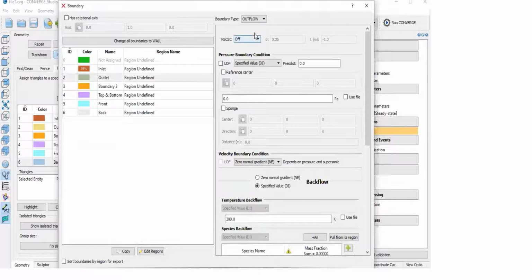For outflow, it will ask for pressure boundary conditions. Here it will not be a total pressure. See, you can't provide total pressure at the inlet and total pressure at the outlet also. It can be a condition like inlet total pressure, outlet static pressure. Or if the inlet is a velocity boundary condition, then the outlet can't be velocity, it has to be static pressure.